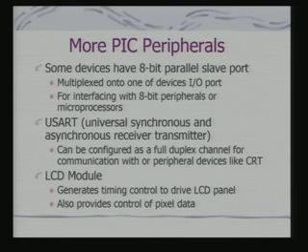It also has an LCD module. The LCD module requires what? A mechanism to do timing control for the purpose of display. So, it provides an interface for the timing control and also provides control of the actual pixel data, because whatever data is being written onto the pixel, how it is to be written, this pixel data would map to a memory area. So, that LCD module has provision for this timing control as well as management of pixel data.